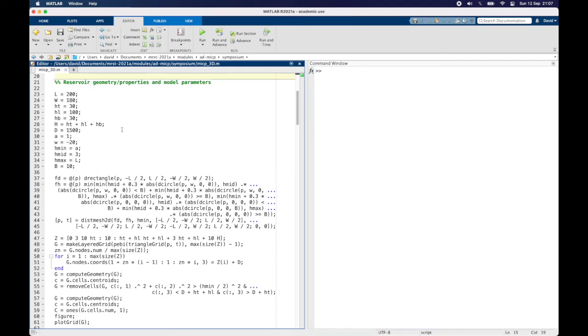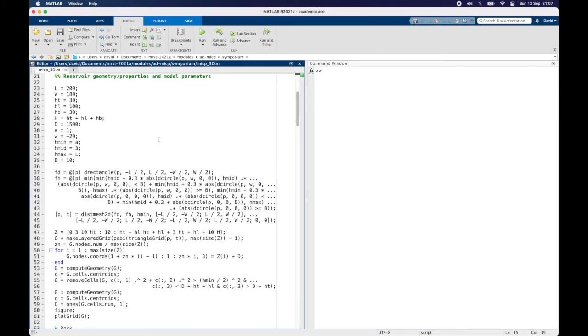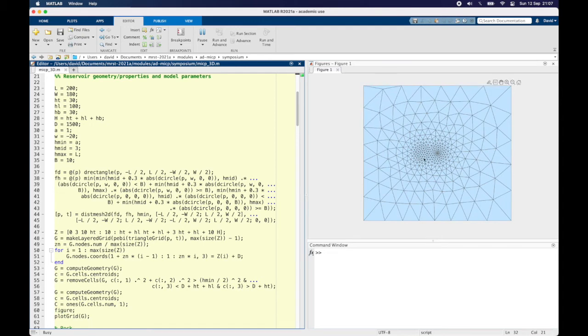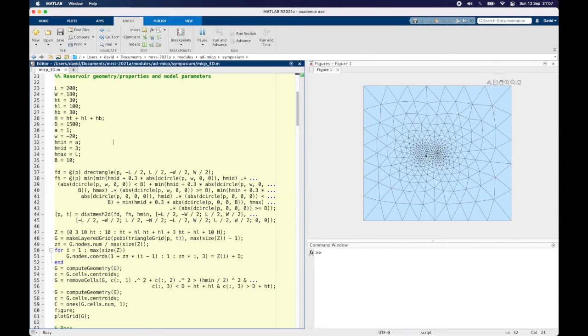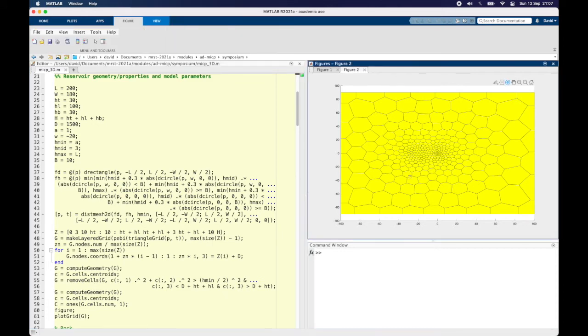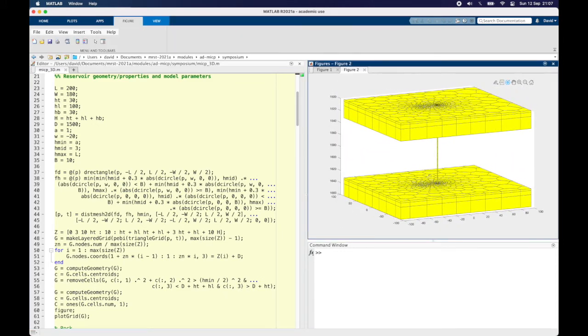So first, we're gonna set up the reservoir geometry. I'm not gonna go into detail because of the time, but basically we'll have one injection well, one leakage path, and an upper and lower aquifer, and cap rock in between. And when we do the grid, we're gonna remove the cells where there is cap rock. So if we run this, here is this mesh where we will have the leakage path somewhere located in this region, and the injection well on the left, and open boundaries on the left and right hand side. So here the grid has been done.